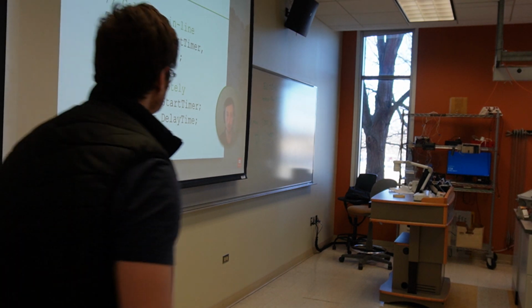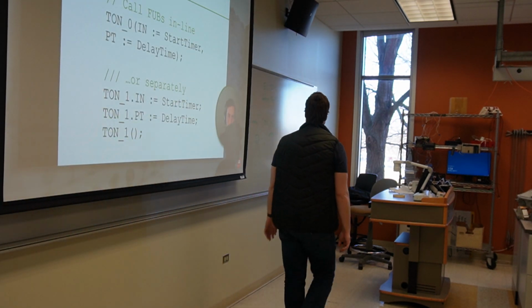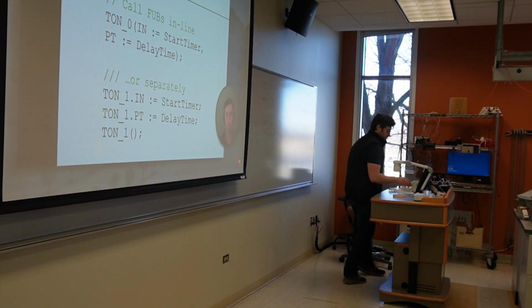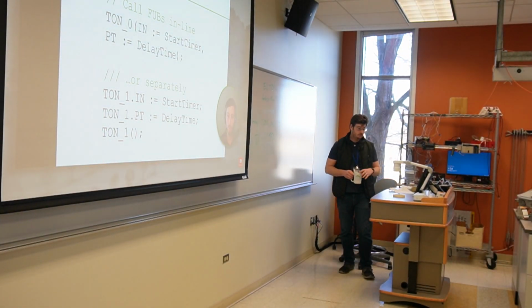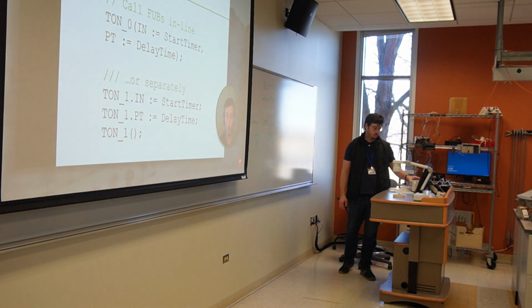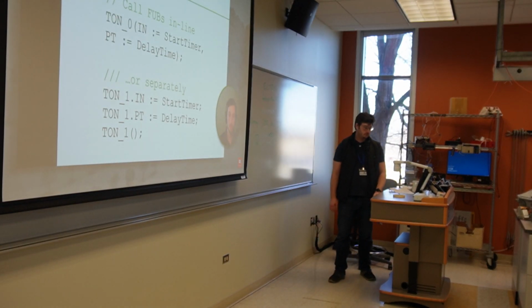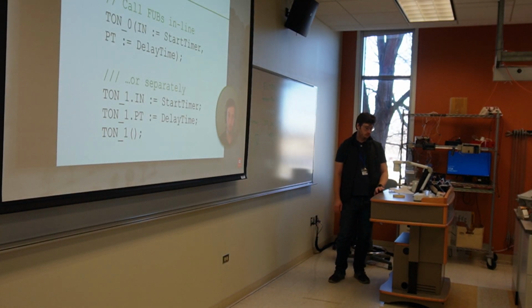the output of the timer goes true. So you can see here I'm using the syntax, the name of the function block, open parentheses, the different inputs separated by commas, and then a closed parentheses. This is the all-in-one function block call. It explicitly calls out the inputs and calls the function block in one line.